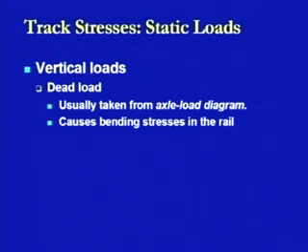Now, this dead load is nothing but the load of the locomotive or the wagons or the things which have been transported. It may be in terms of passengers or freight. So, we have the load of locomotives or the loads of the wagons in terms of the axial loads, and that is to be taken as a dead load. The other load will be the live load.